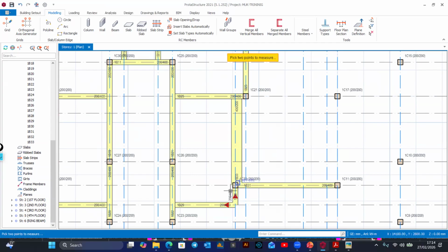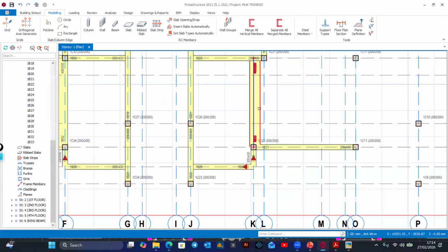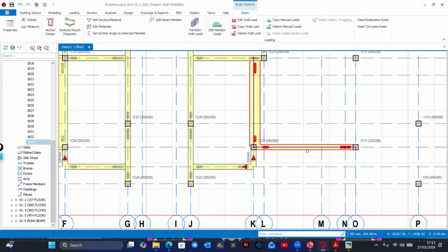You measure from this point up to this point, how much do I need to move? -50. Okay. Then you can double click on that element and use this E1, E and then EZ. Just enter the distances there.